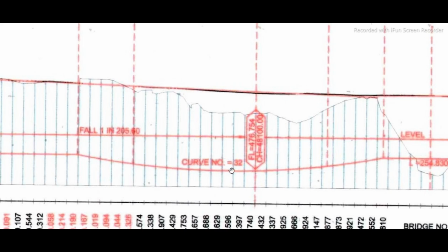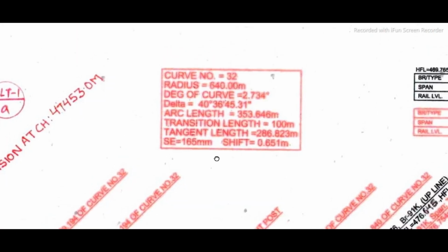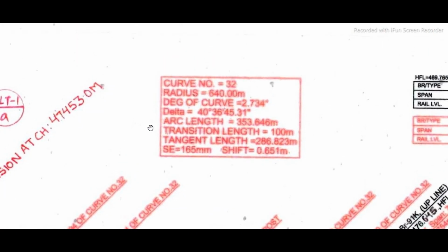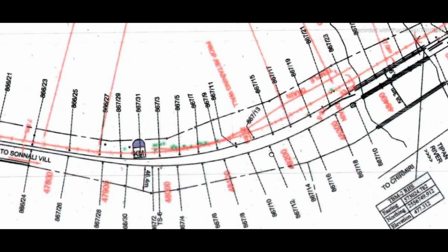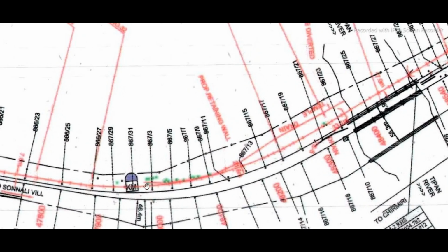Concept of grade compensation. If a horizontal curve exists along with a rising gradient, the pulling power of the wheel reduces. Hence, to increase the pulling power, the gradient is reduced to compensate for the loss of tractive effort. This reduction in gradient on a horizontal curve is called grade compensation. Compensation for curve on gradient.